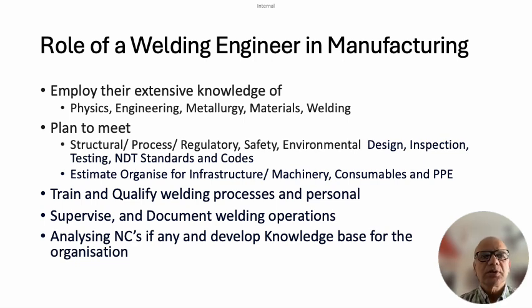So the first role of a welding engineer is to really understand the physics. Now, what we mean by physics: whether it is a structure, a pressure vessel, a reactor, a heat exchanger, what is the end use, what is the purpose of this particular equipment, what it is going to really operate for, and what the intended service applications and the service lifetime are.